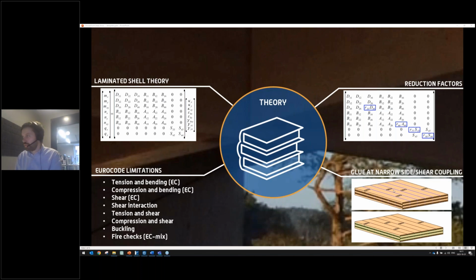in the check. Another option is to have a shear coupling, and that is normally always the case. The shear coupling is between each plank layer in the CLT panel. In here we see it illustrated by the light green color. And if you don't have any shear coupling, each layer will work individually without any shear connection between the different layers, if that makes sense.